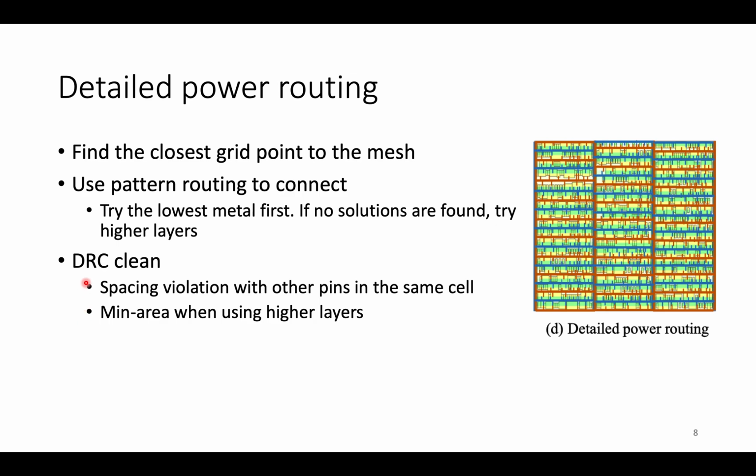There are two major violations we are facing. The first is a spacing violation between the wire we're going to place and other pins in the same cell. The second is the min area violation when using higher layers.